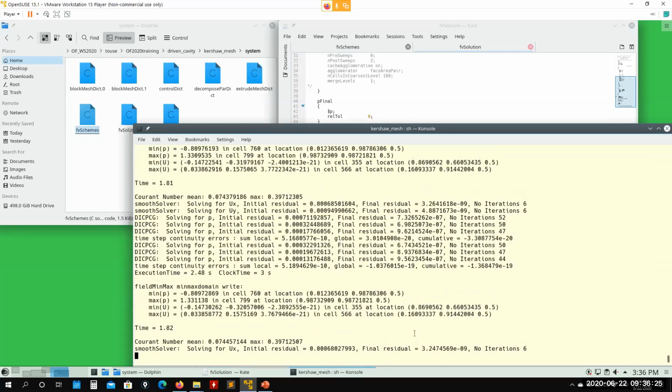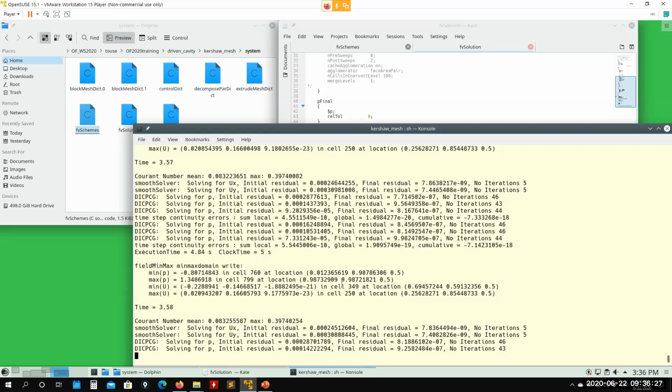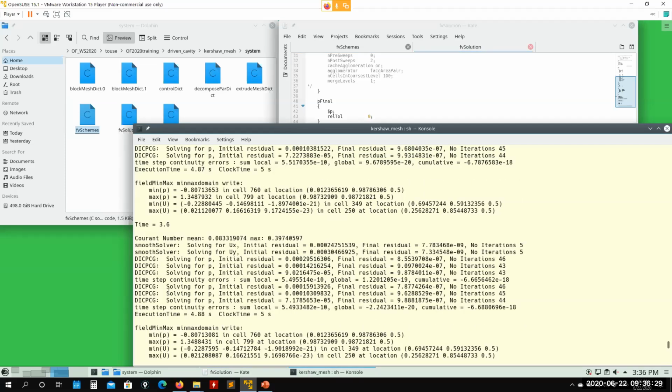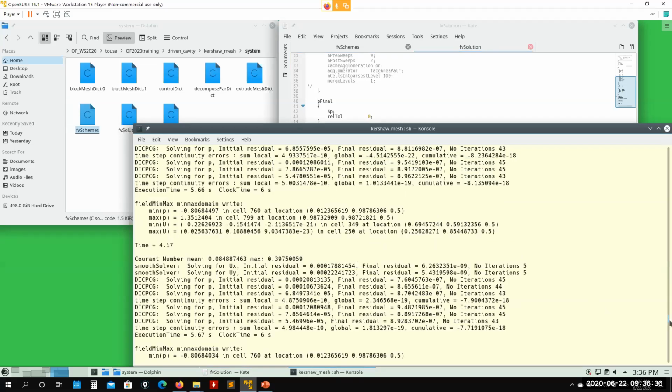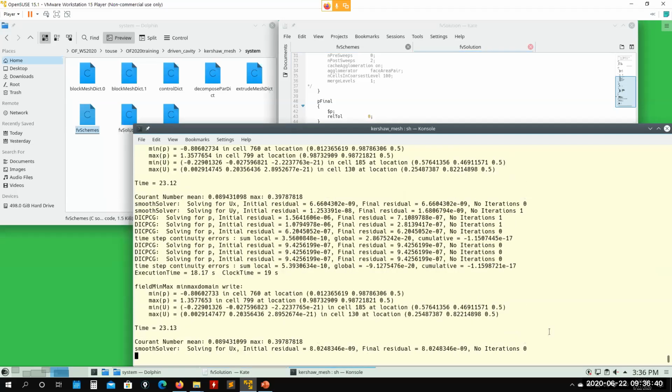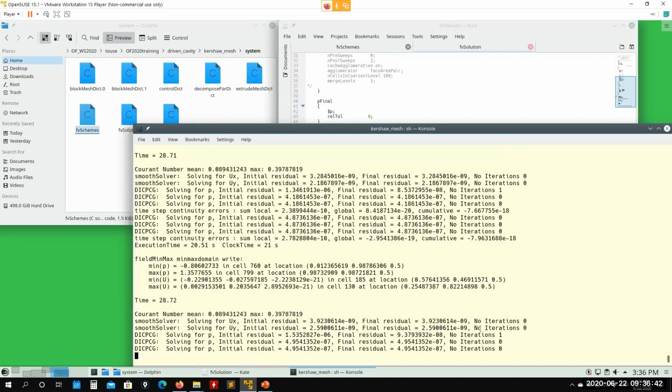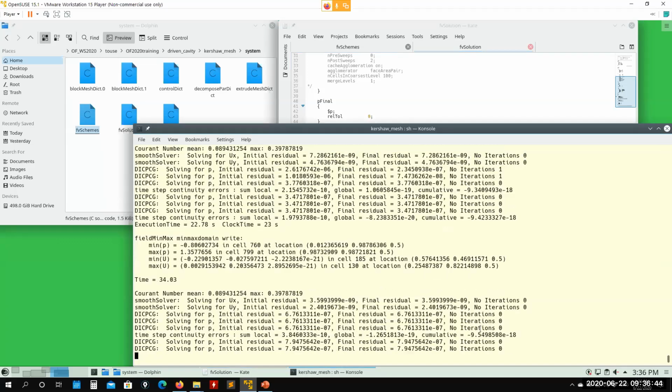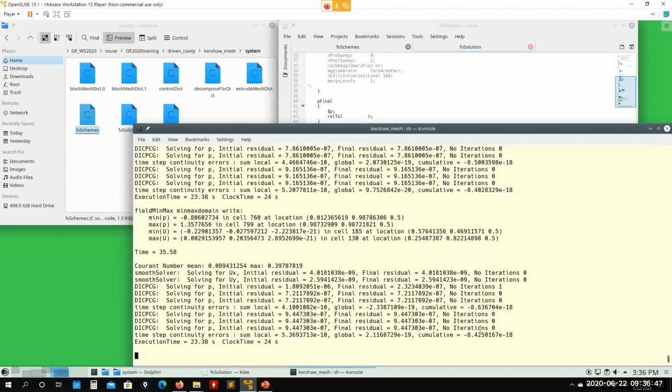It will be slower than the previous one because it's now doing 2 iterations. See that here you have iteration 1, iteration 2. If you put 3 there, 1, 2, and 3, those iterations might be expensive, but you are gaining stability. And that is my advice: do not sacrifice accuracy and stability for computing time, because you might get the wrong solution or it might diverge.